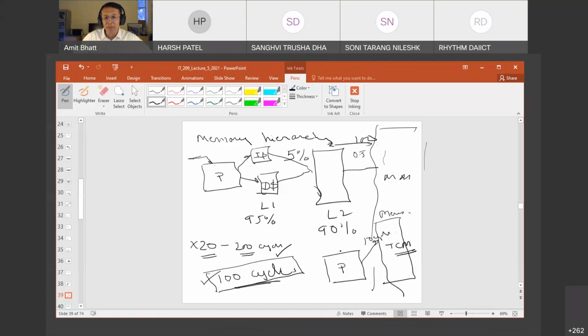So most of the small embedded processors are by necessity of this type: there's a single memory, and then there is a small ARM7, ARM9 kind of processor. I mean, it can be used as a real-time processor, but a real-time processor has to have a lot more than just this. It has to have the guarantee of manufacturing, guarantee of no manufacturing defect, and many other things. So testing is much more important if you want to sell this processor as a real-time processor. But otherwise, many of the low-cost processors are of this type. You don't call them real-time processors, but this is how it is. Single memory and processor.